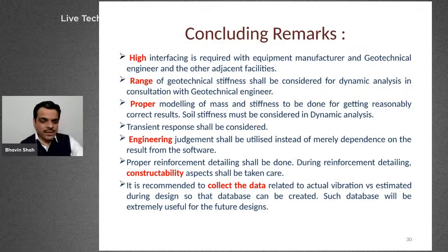And the last point I have mentioned is that it is recommended to collect data on the actual vibration versus the estimated vibration during the design cycle, that is, the vibrations from whatever computer analysis we have done, compared with the actual vibration of the machine. That kind of database will be extremely useful for future designs.